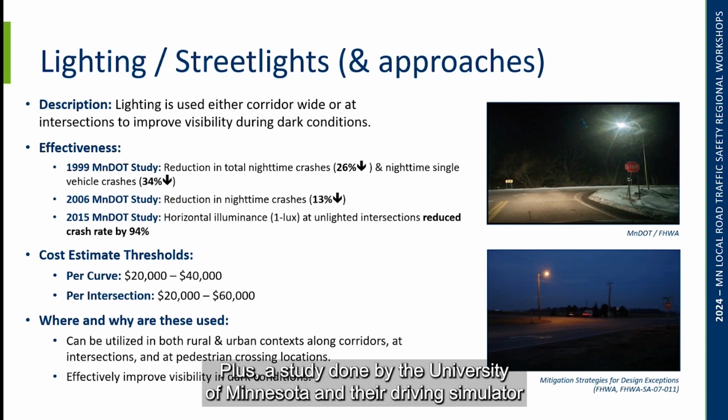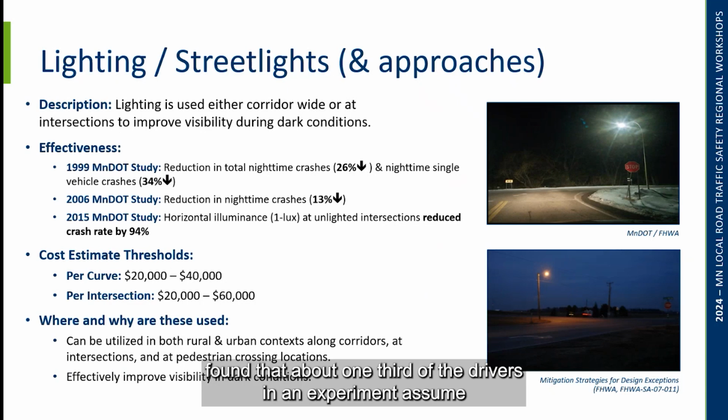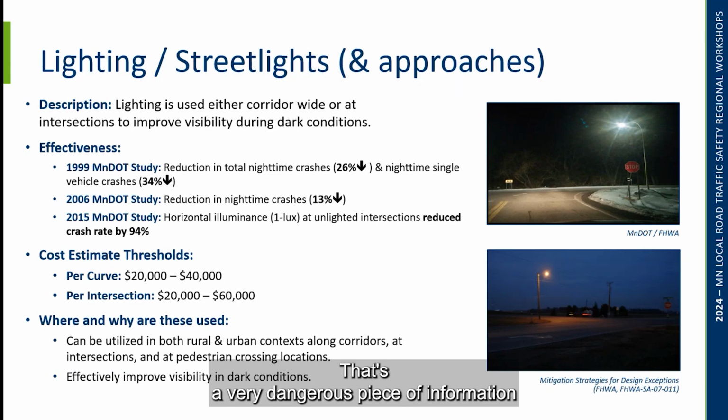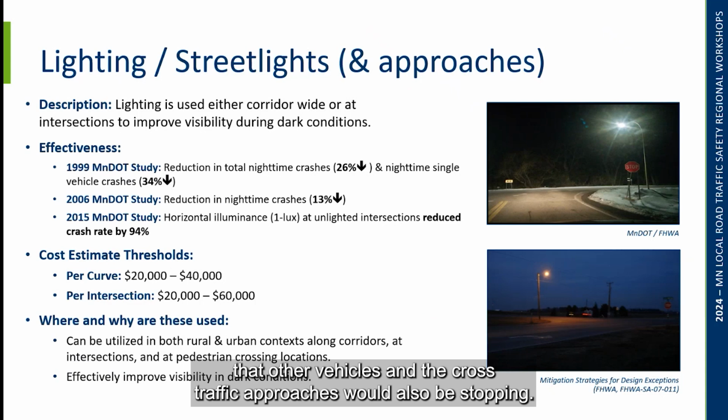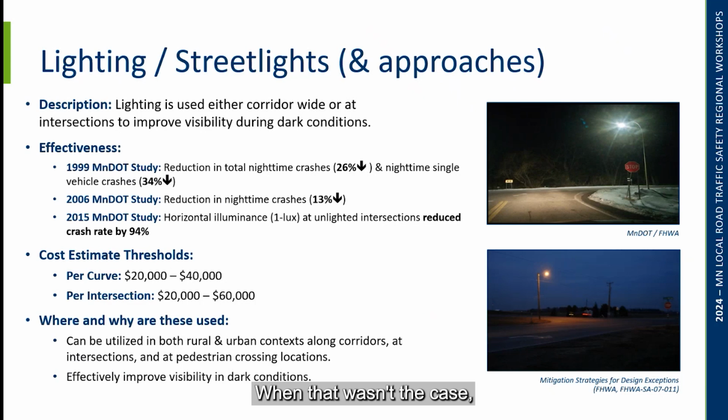Plus, a study done by the University of Minnesota in their driving simulator found that about a third of the drivers in an experiment assumed that the presence of an overhead flasher indicated an all-way stop. That's a very dangerous piece of information to put in the mind of drivers, because then drivers are assuming that other vehicles on the cross traffic approaches would also be stopping when that wasn't the case. Some studies have shown a reduction. Other studies have shown an increase.